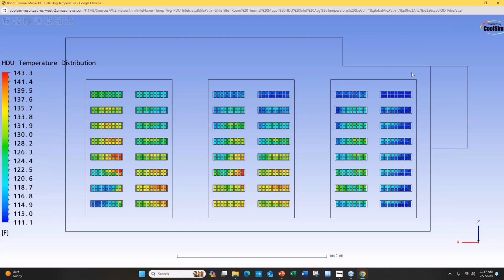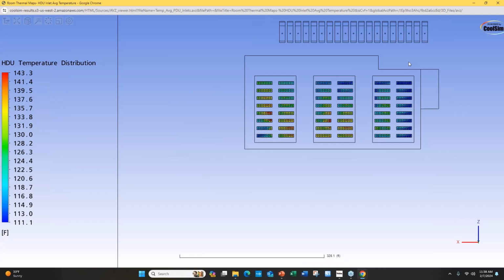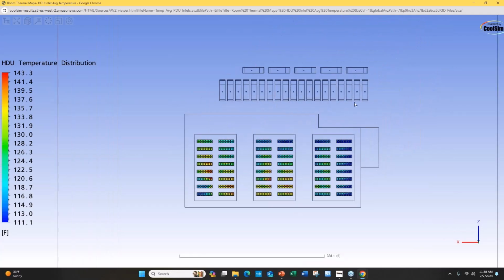What would you take to considering the windrows of different probability of wind? Consider the maximum speed. Which is the maximum. Well, you can consider a lot of different things with the windrows. The windrows just simply gives you an idea of what to look for. It is a discussion with the customer about, at the end of the day, what they're most interested in. It often has to do with the orientation of the building and the location of these devices with respect to the building. So in this particular model, you've got all of these generators sitting out here, yet we're looking at a wind coming from, in this case, the right-hand side. That's because it's the prevailing wind. But another study I would want to do here is this direction.